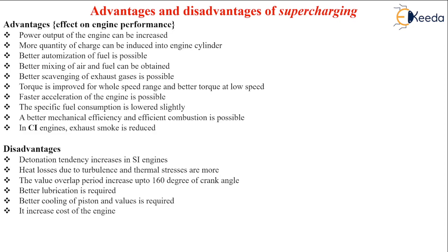It has to have some disadvantages, which can be enumerated as follows. Detonation tendency will increase in SI engines, as we have already discussed right at the start of this lecture. Then heat losses due to turbulence and thermal stresses will be more. Also, the valve overlap period, that is the time or the crank angle degrees for which both inlet and exhaust valves remain partially open, will increase, and it may go up to 160 degrees of crank angle rotation.